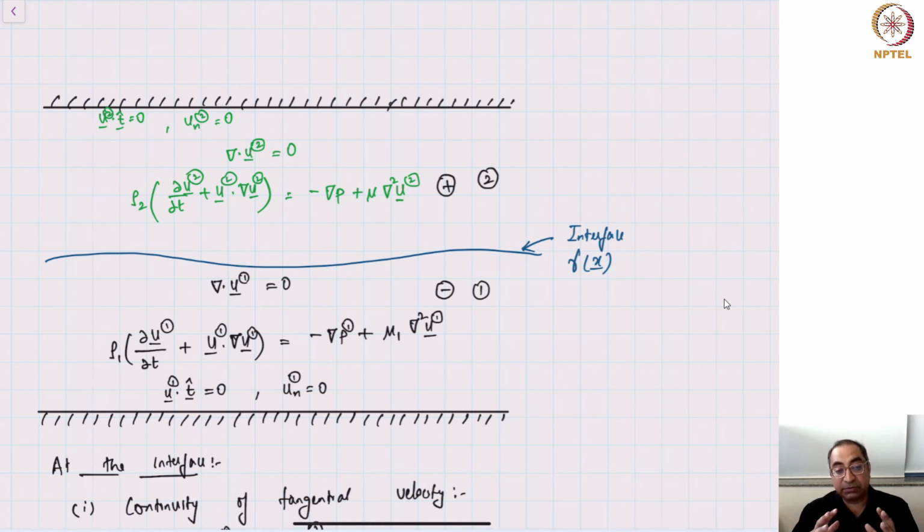Free surface flows are problems where there is an interface, so you have to deal with surface tension, but you don't have to deal with it as a two-phase flow, but as a single-phase flow, where you don't worry about solving for mass and momentum balance in the other fluid. The other fluid is only providing a constant pressure. It is passive. In no other way does it affect the flow in the bottom. We will deal with these free surface flow problems as well.